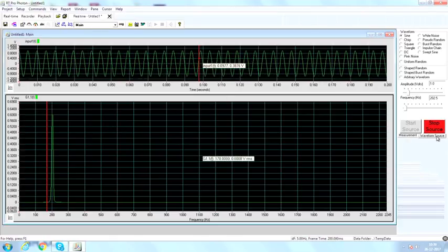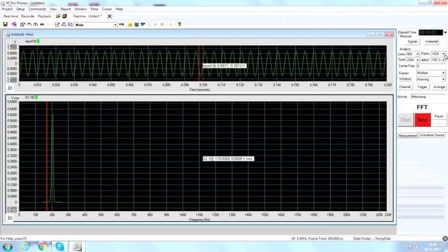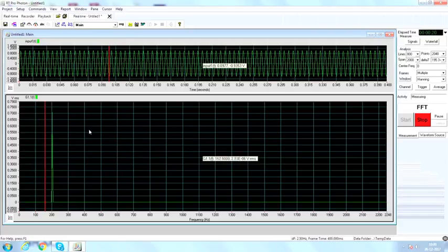And how can I change that? I will just go to my measurement and increase this to 800. Okay. Now, you see it becomes 800, then this becomes 0.4. So, delta f would become 1 by 0.4, that would be 2.5 hertz. Now, let me see, if I do the measurements, you see here it is 87.5, 90. So, I have got delta f as 2.5 hertz.